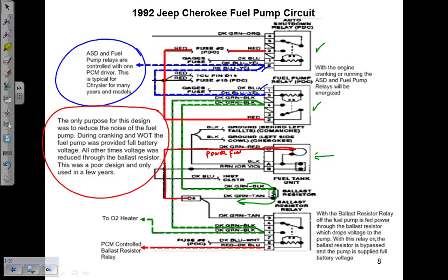So now think about the symptoms. Crank, start, run, stall. That's what it would do every time. Crank, fuel pressure, it would start. Fuel pressure drop, it would stall, and what was happening was a bad ballast resistor on the car. That was what was wrong with the car. So be careful. Again, system designs, you have to be aware of things like this.